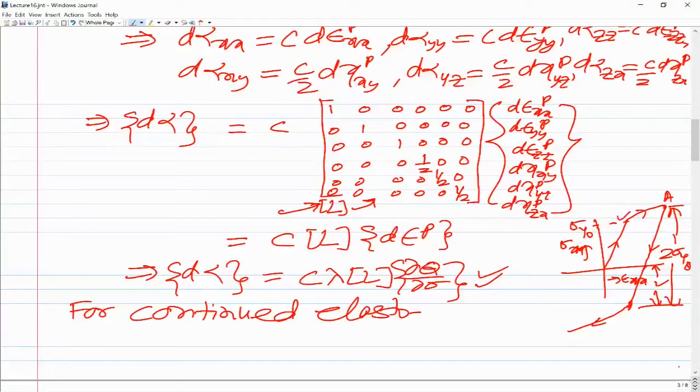So that is translation of a yield surface. The origin of the yield surface changes. If the initial loading is in tension, then the yield surface translates in the tension side. If the initial loading is in compression, then the yield surface translates in the compression side. So alpha denotes translation of the yield surface, and in effect it is modeling the material aspect where the yield stress is different in tension and compression.